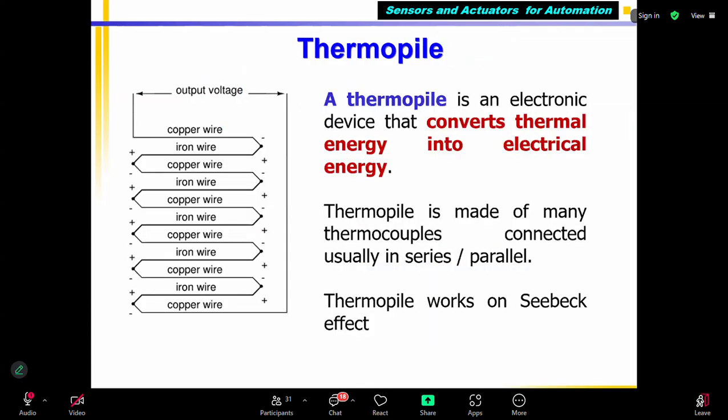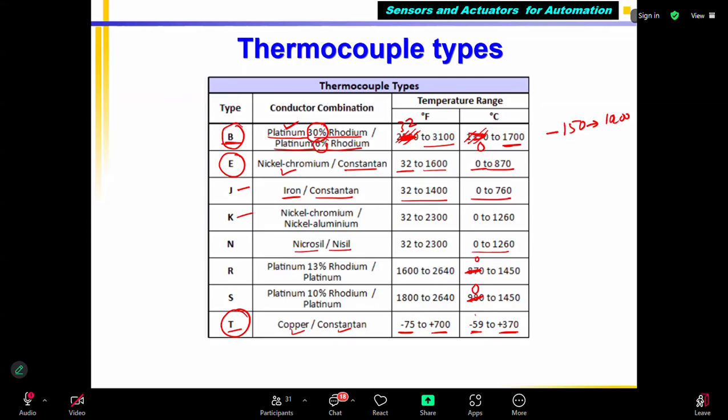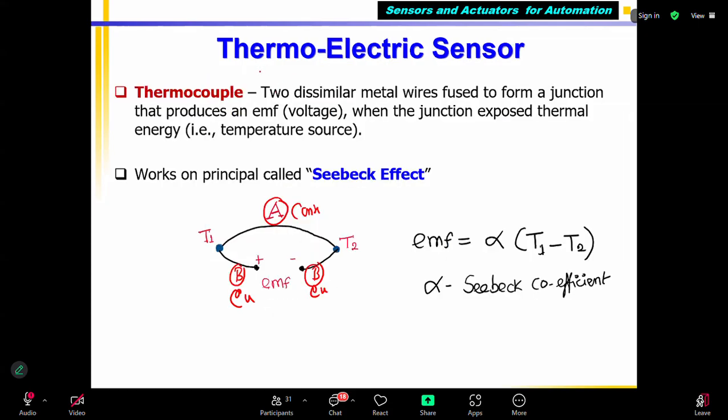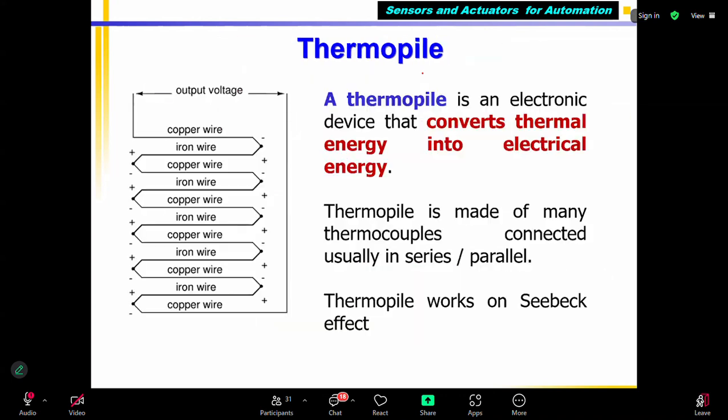Okay, so this is how the thermocouple works. This is based on the Seebeck effect, which is called a thermoelectric effect sensor. This is the last stage. Then if I connect multiple thermocouples, for example, this is one thermocouple, this is another thermocouple, you can see that if I connect multiple thermocouples in series, it can generate high voltage. For example, one thermocouple, one junction, Cu and constantan, correct? One junction is formed. If I vary temperature 0 to 400, it may measure, say, 40 millivolts.